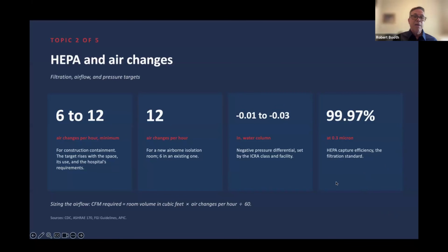I recommend that at the beginning of the project, you verify it's HEPA filtered, right? And then also at a periodic time based on the hazard of that area. So if you're in an operating room, I would check the particles every day. If you're exhausting into a lower risk area, and you're comfortable that the machine is working properly, then you can do it on a weekly basis. Most people do verify that on a routine basis, anywhere from a day to 3 days to a week. So it's based on hospital policy.